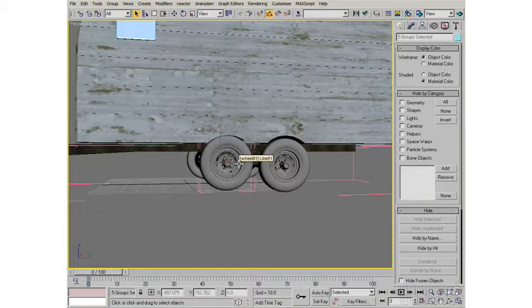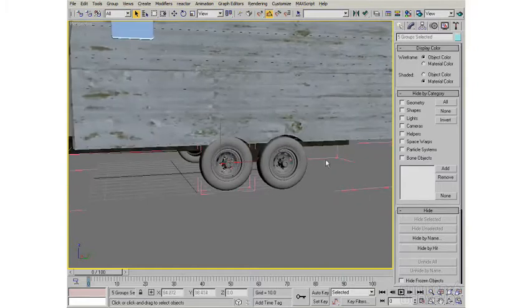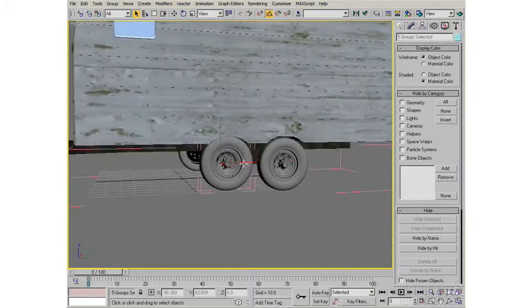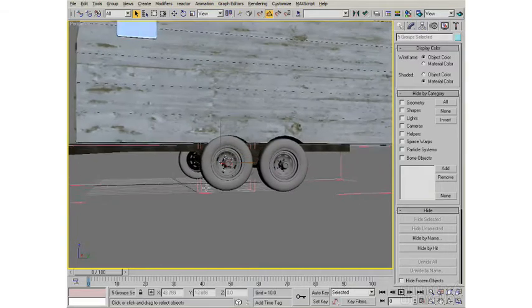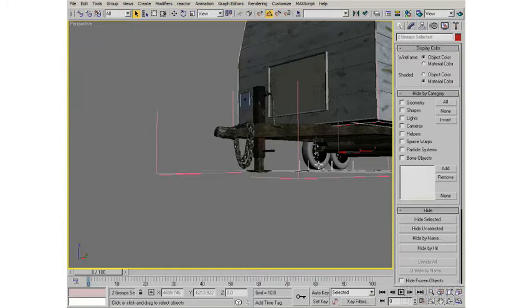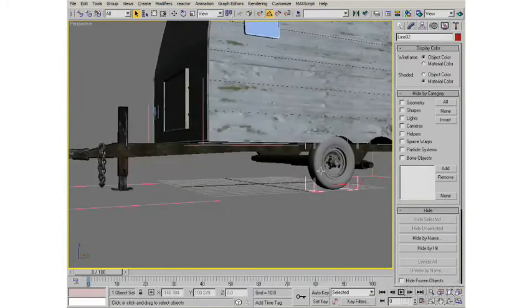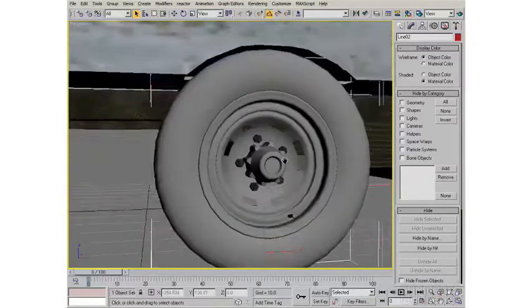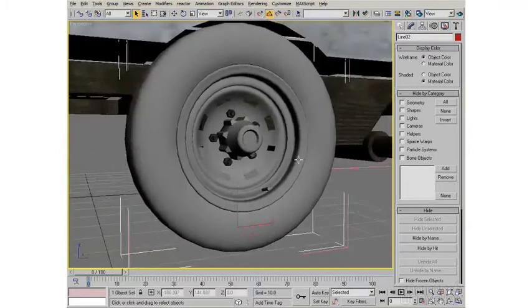You could potentially go in and, as you model it, assign a placeholder material to each piece. That way, when you instanced it and you applied a material, or you edited the placeholder material for each one, then it would update on each one because they already had the material assigned. So if you had some foresight, you could do that. Unlike me, but I'll just go in and I'm actually going to take each one of these out, and I'm just going to delete them. Then we'll re-instance them once this one has materials fully applied to it.